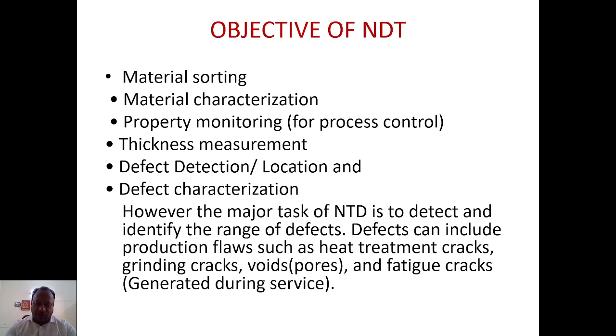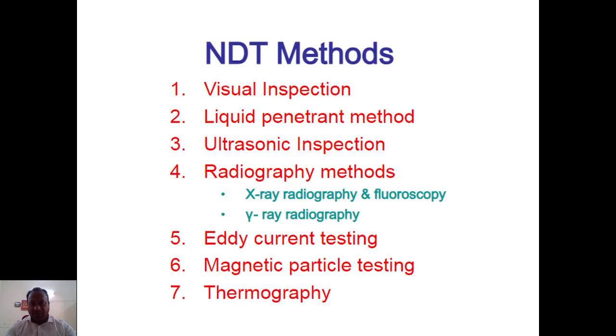So pores, fatigue cracks, and grinding cracks, all these we can analyze with NDT using ultrasonic testing, radiographic testing, dye penetration testing and liquid penetration testing. The NDT methods we use are visual inspection, liquid penetrant method, ultrasonic, radiograph, eddy current, magnetic particle testing and thermography. By visual inspection, we cannot see the depth of the product defect, so we need to go to the remaining NDT methods.